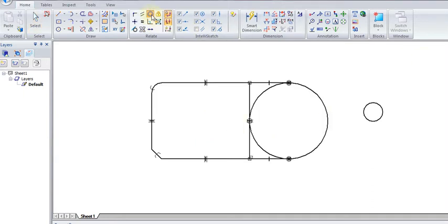So we go to our constraint relationship, our concentric relationship, sorry. We select the small circle first, and the second circle, the larger circle, is what we select next. Now we see that the smaller circle has now been constrained to the center of the larger circle. So we've now created this relationship with the large circle. So it's very important to remember with the constraints, with the relationships, you want to select what you want to adhere to the constraints of another part of geometry first, and then select the other part of the geometry second.